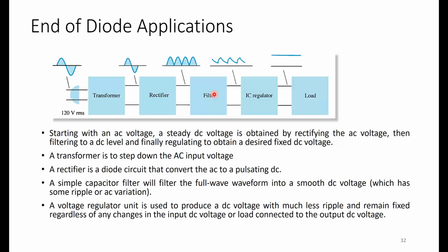huge in the sense where you have to look at it comparatively, because the capacitor will cause tau, which is equals to RC, so the charging and discharging will somewhat improve the pulsating DC, but it will still have some kind of ripple before it goes through our Zener regulator, because our Zener regulator can tolerate changes in Vin, but it will maintain an output load at a standard DC value, and this DC value is VL, that is the Zener voltage VZ.